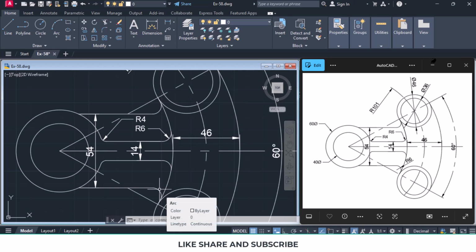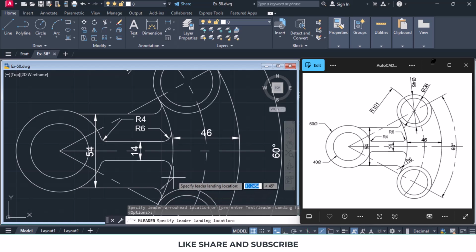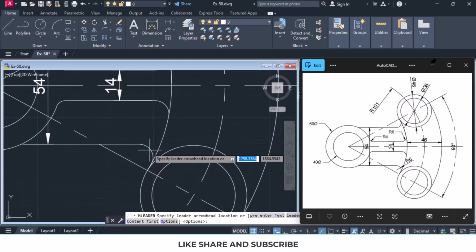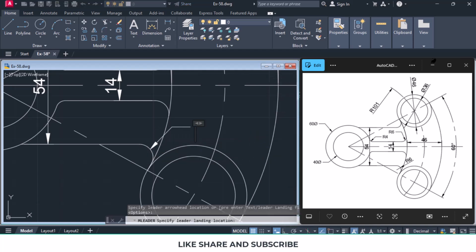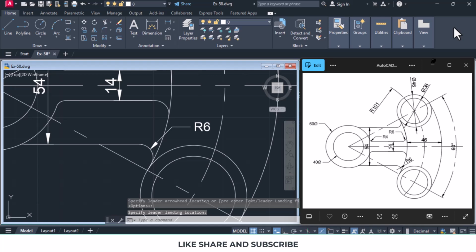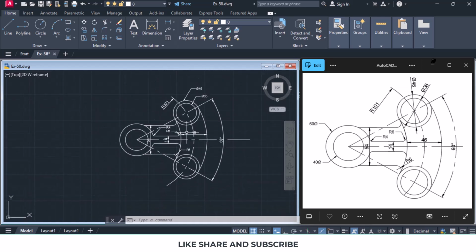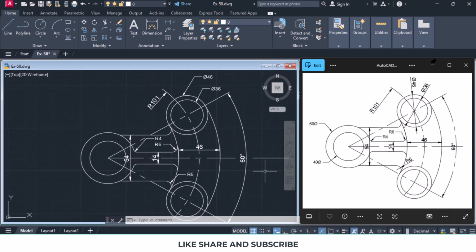So again leader dimensioning, click over here, ensure that you touch the object. So leader dimensioning and click over here and R6, close. So this is also done and our geometry is now complete. So friends, in this video tutorial we have seen how to make this geometry in AutoCAD.